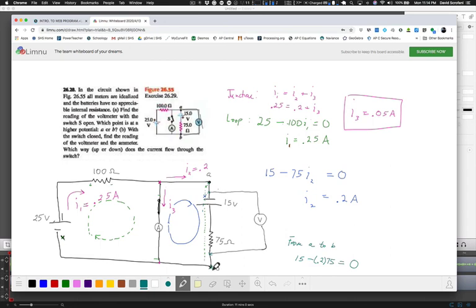No voltage difference. In other words, the voltmeter says literally 0. That's significant. And of course that's the case, because look, there's a bare wire connected from point A all the way around to point B. Remember, idealized ammeters have no resistance inside of them, and neither does a switch, and neither does any of the wire.